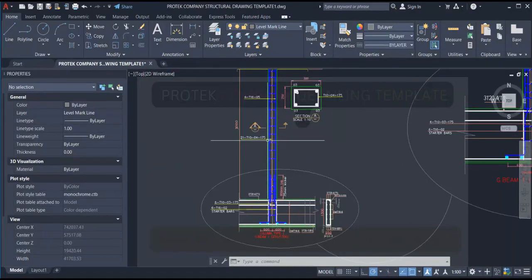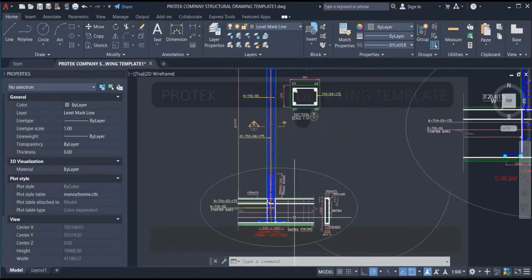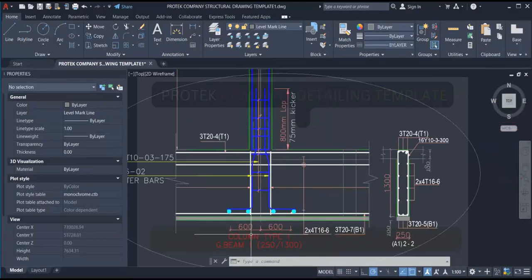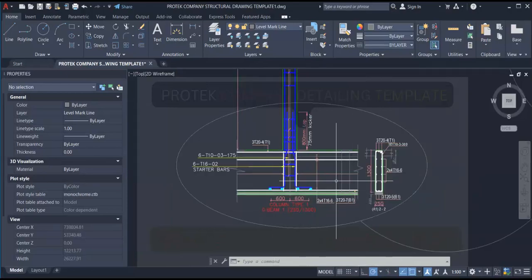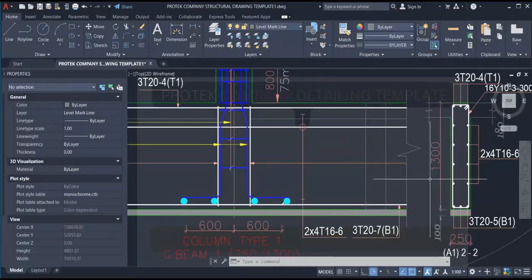We are going to be presenting the details of reinforced concrete columns when Raft on beam foundations is being used on a structure, just like the model I showed not too long ago in Prokon Structure. So here is the Raft beam. This is the Raft beam, or you can call it foundation beam. You can also call it ground beam. And it is up to 1.3 meter height.